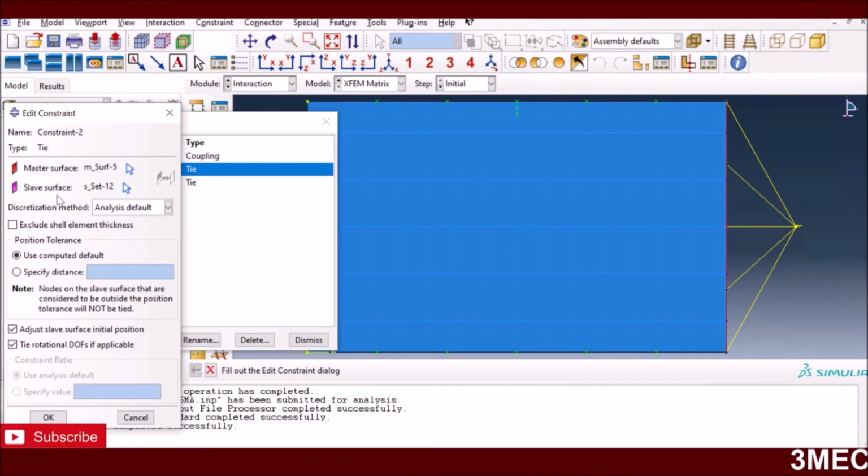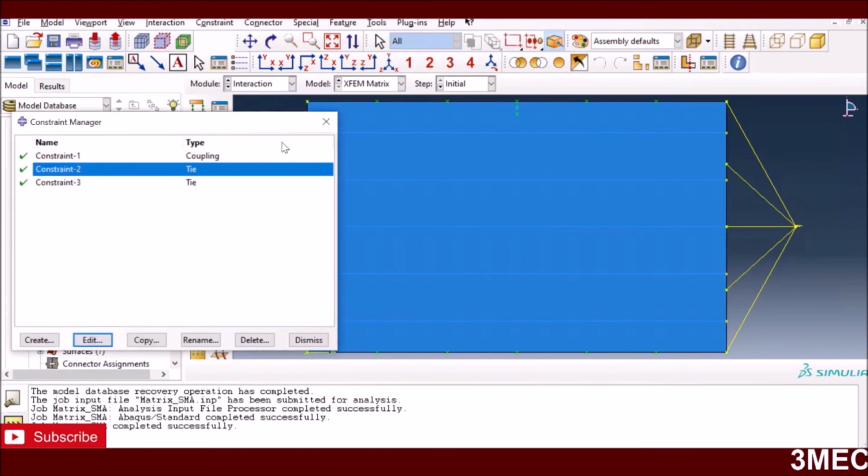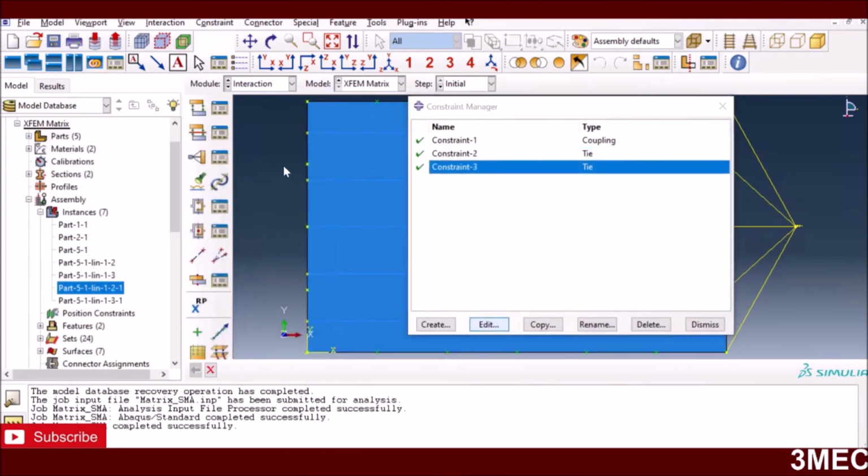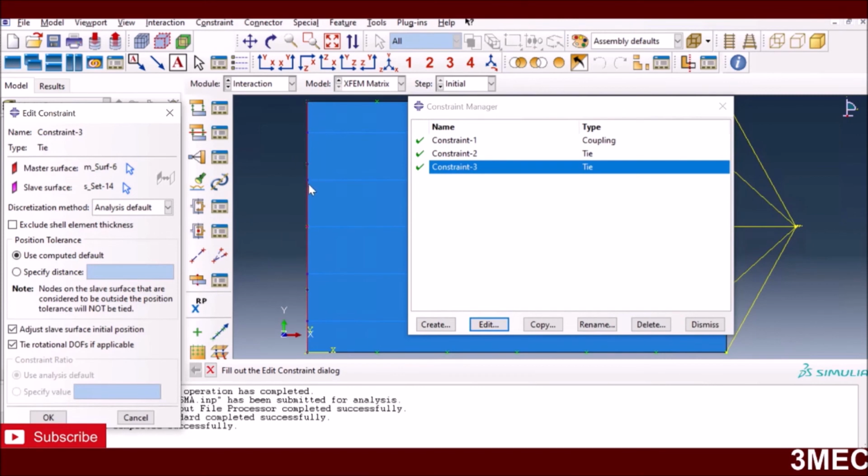Generally the softer surface is assumed to be the slave surface, so again you can decide which one is softer in your case. And that's what I have done on the other side as well. If you look at the other side, I click on this and then you see it gets red again. So I first created the node set for the fibers, and then I created the surface, and then basically I just defined them in the interaction.